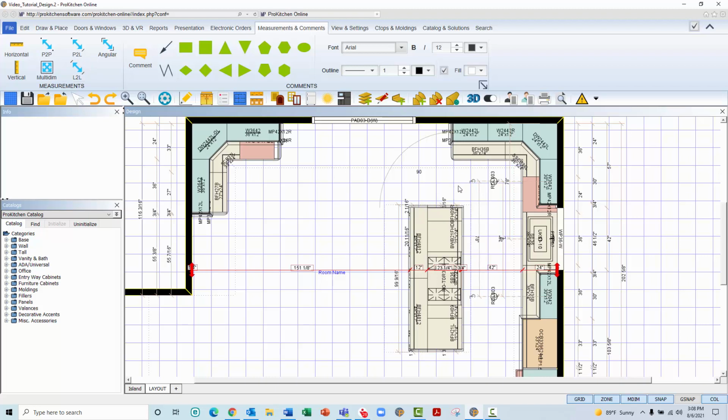Again, navigate to the ribbon. Left-click the L2L icon to grab the tool. Move the mouse onto the plan view and hover the mouse at the front of the base on the perimeter of the design. Once the familiar purple line appears, left-click to start drawing the dimension.